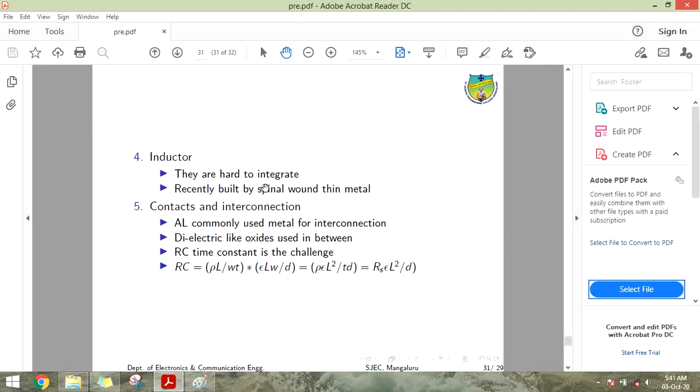Metals can be aluminum or copper depending upon the heat each is subjected to. The multi-layer metals are incorporated with dielectric in between. The dielectrics deposited are oxides, borophosphosilicate glass or nitrides. Borophosphosilicate glass is used for planarization. Planarization is required to prevent breaks in the metals.